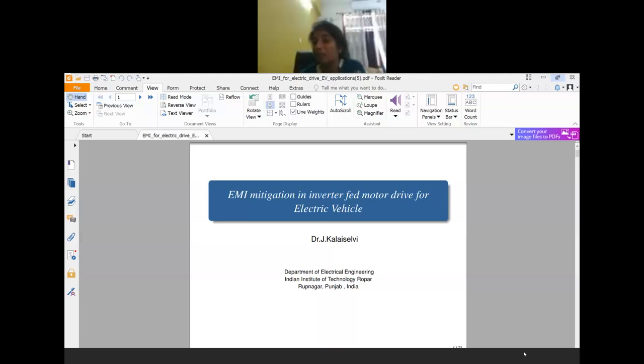Ultimately, any product you make has to go through the standards for a particular thing, whether Class A, Class B, Class C, or industrial. Say for example, industry applications don't require much of an EMI standard, but household appliances and electric vehicle CISPR standards are strict. So whether you have a precise measurement or not depends on the application. Say for example, I am measuring 5 ampere current at 50 hertz. What is my maximum bandwidth required? What is the accuracy required? This is what I would look at.